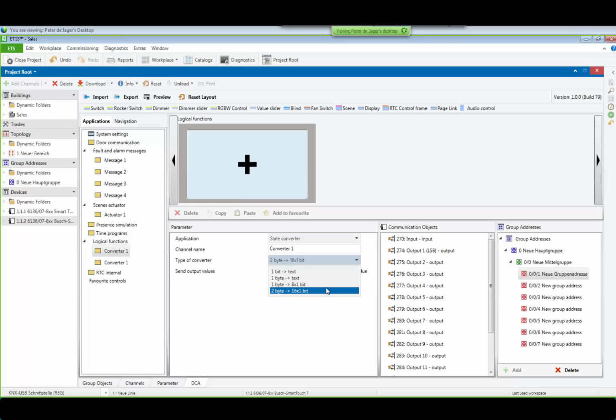They often have a fault telegram, and in this fault telegram there are different faults. Faults can be combined in one telegram, and every bit of this byte or 2 bytes stands for a different kind of fault message. For instance, overheating or lamp failure and so on.